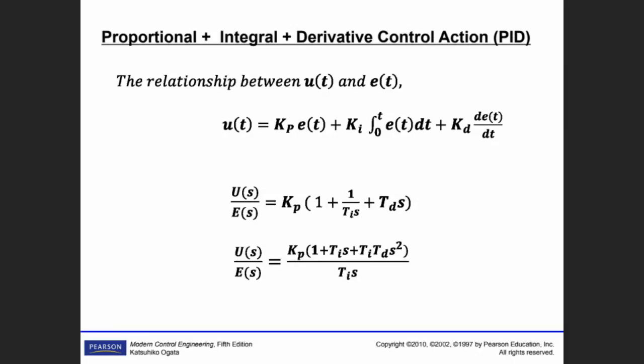However, the integral controller integrates the error and then gives you the output. Of course, the integral controller never forgets the error, integrated since the start. And also the derivative controller gets the derivative of the error, so it predicts future oscillations and things like this beforehand. So these three together, we already discussed the effect of those, but now we are going to design it.